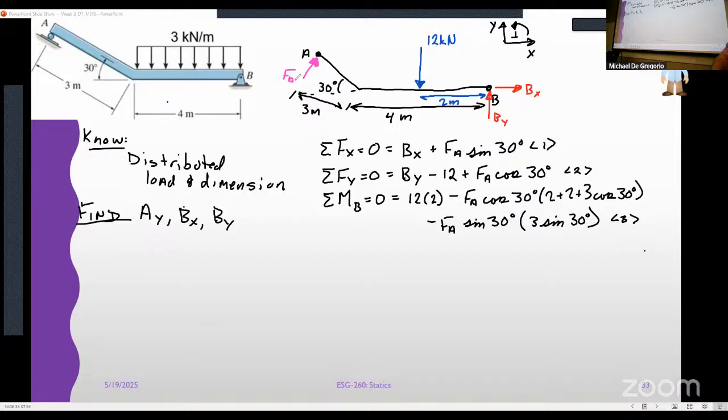When you set a coordinate system, we need to report everything in terms of that coordinate system, where x is horizontal and y is vertical, not angled. Had we angled it at 30 degrees, there would be 3 other forces that I need to do trig on instead of essentially one force that needs the trig treatment.